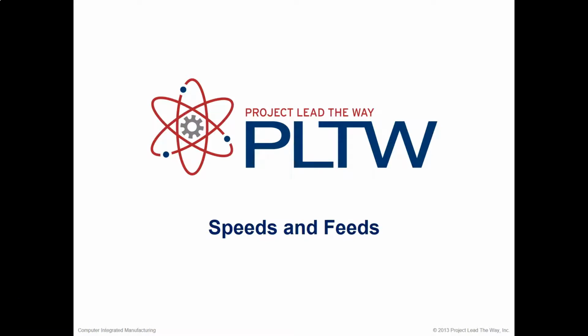Let's talk about speeds and feeds. These are very important. All of our CNC machines in the Fab Lab utilize these to some extent. For our laser cutter, we think of speed as how fast the tool moves around on the X and Y axes. But instead of a feed rate, we consider the power at which the laser is fired. Our 3D printers consider the feed rate to be how fast the spooled material is pushed through the hot end nozzle, and speed is like the laser cutter, how fast the nozzle moves.